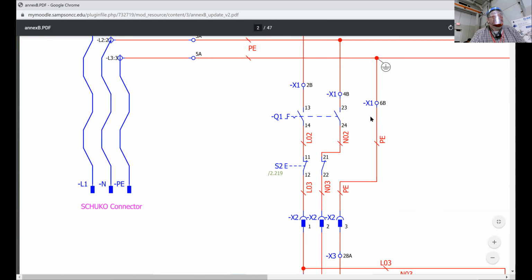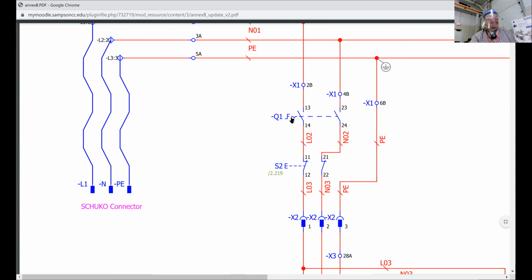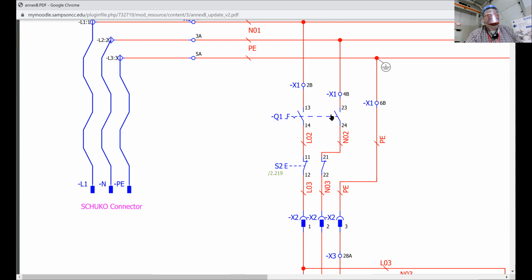Anyway, what were you saying the V was? Just a push button symbol? No, the V is a detent. It's a locking mechanism for a switch. So that's the giveaway: is this a push button or a switch? The little V symbol means it's a switch.